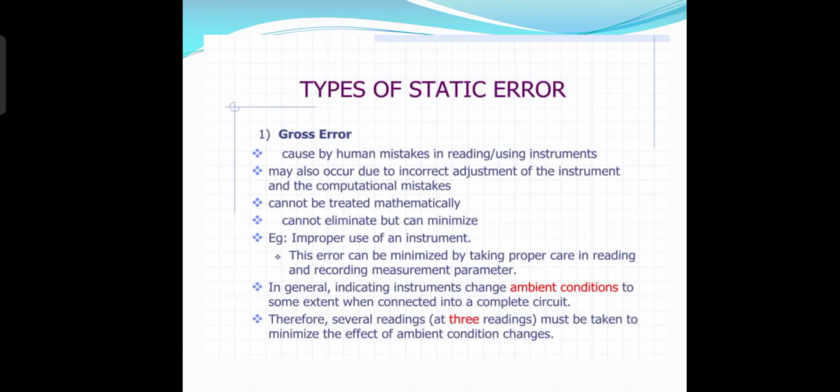In general, the indicating instruments change with ambient conditions to some extent when connected into a complete circuit. Therefore, several readings must be taken to minimize the effect of ambient condition change.